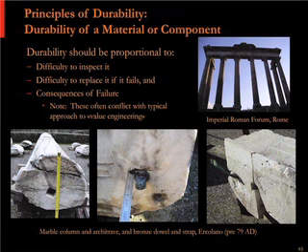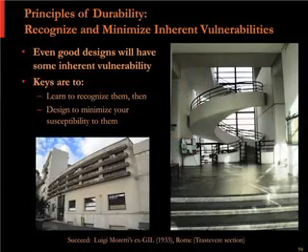On the other hand, if you think of a structure like this, any of the temples in the Roman Forum or in any of the Roman towns, really, kind of massive stone construction, way up high, so difficult to get there. These connections would be doweled together. Sometimes down at grade, on say a plinth or steps, you would see iron cramps or dowels used. The iron corrodes, but when you get into a situation like this, very difficult to get to, very difficult to replace if it ever fails.